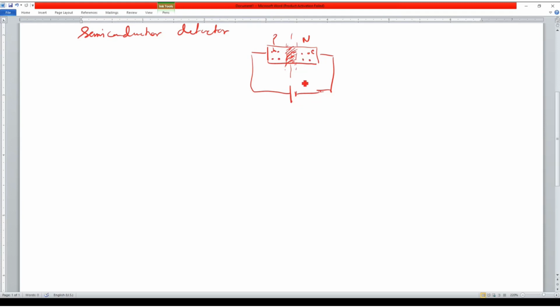सिलिकॉन के लिए 0.7 के आसपास का होता है आपका एक्टिवेशन वोल्टेज, और 0.3 होता है जर्मेनियम के लिए. But 0.3 and 0.7 are not the energy band gap. कई बार बच्चे कंफ्यूज होते हैं और एनर्जी बैंड गैप को ही बता देते हैं कि ये हमारा वैल्यू 0.7 या 0.3. But for silicon it is 1.1 or 1.2 roughly. नॉर्मली 1.12 होता है इलेक्ट्रॉन वोल्ट में सिलिकॉन के केस में, और जर्मेनियम में 0.69 होता है.